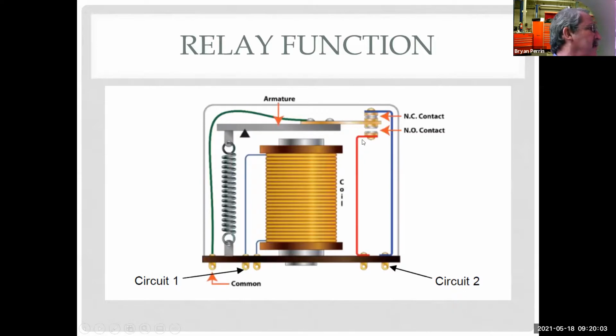Right? Because I'm not going to drive with my high beams on all the time. So I'm only going to use the relay to turn on the high beam, so I don't need as big a switch. And I use the relay to control it. I'm feeding power through here from my low beam all the time, and if I turn to high beam, I energize the relay and I get high beam. So that would be one example where I have a default position that doesn't require any electrical power, and then a position I don't use as often that does require electrical power.